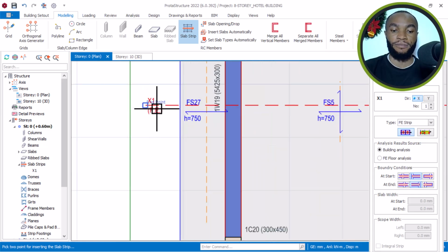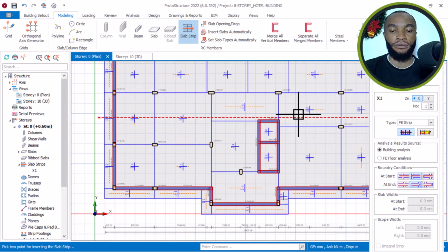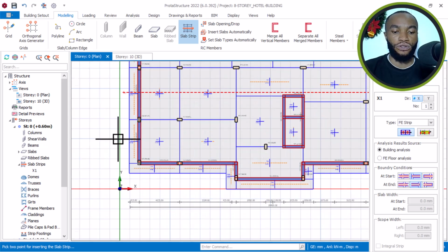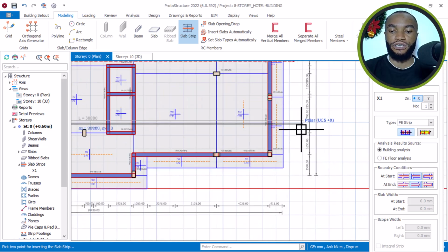Okay, that's fine. So with this now, I'll just cut again. Now I have cut through this panel. I will then go again and cut, hold my control key, click on this place first, come here, hold my control key, and then click here.